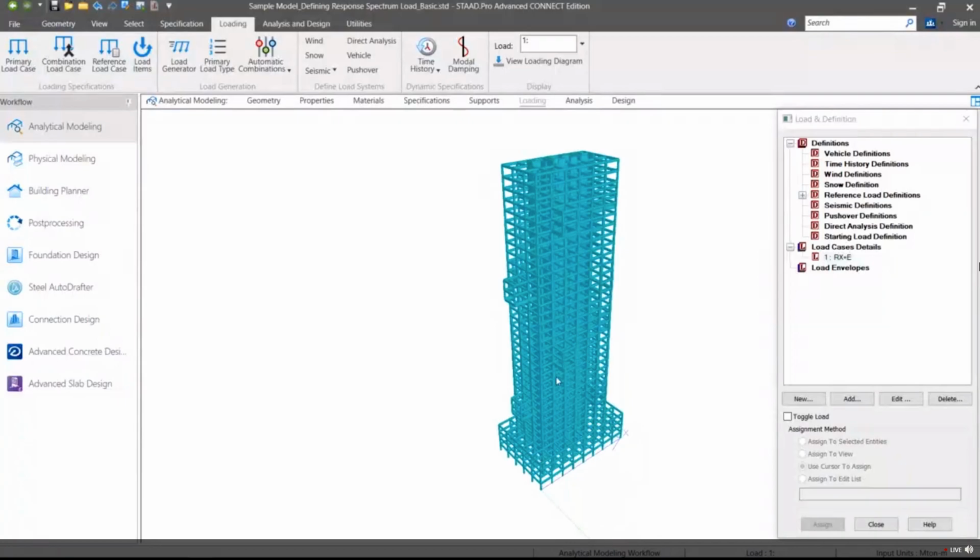Peak story forces at each diaphragm level are mentioned next. Here, the story shear value in Z direction is 0 as the load is applied from X direction only. Next are the torsional results. The plane dimension of the floor is used to calculate the accidental eccentricity value, which is 0.05 times the plane dimension in the perpendicular direction of load.